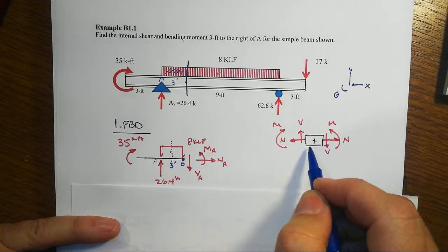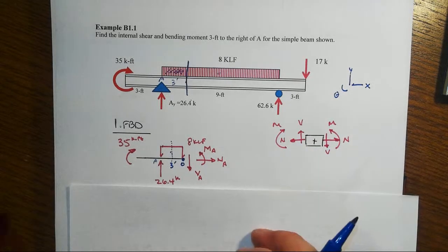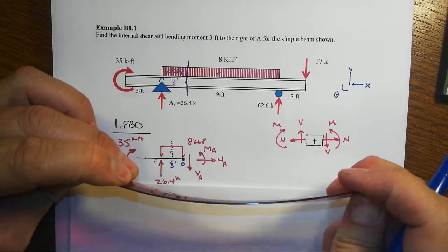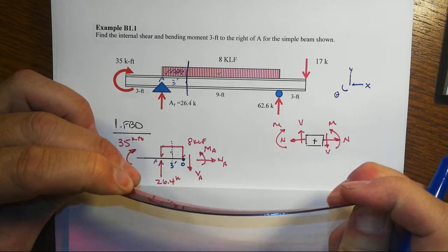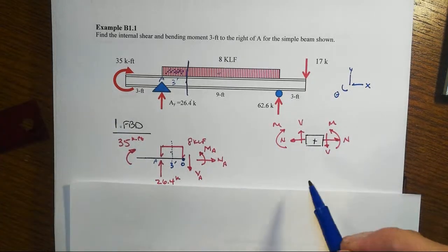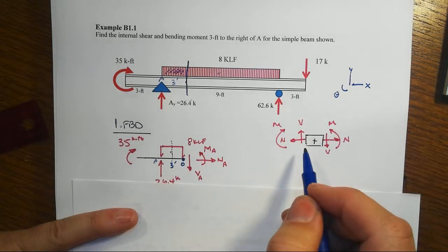3 different sign conventions that you have to keep track of. Right? And so I keep this little drawing around all the time here. The only one that I remember easily is positive bending moment, because positive makes me happy, and then I usually smile when I'm happy, so therefore the beam curves concave up, and these are the moments that would go along with that.